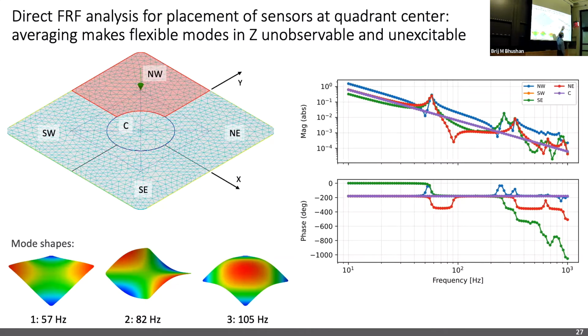And then we get the response like these. So it shows behavior of all the modes as well as the phase response. Once we have that, suppose I want to get the z direction from these measurements. We take the average of these 4 quadrants. That gives me the z direction. Theta x would be the average of these two minus these two at the bottom, so on and so forth. So I can transform these coordinates to get the z, theta x, theta y, as well as the bow direction. The bow direction is the center measurement minus the average of these 4 quadrant sensors.